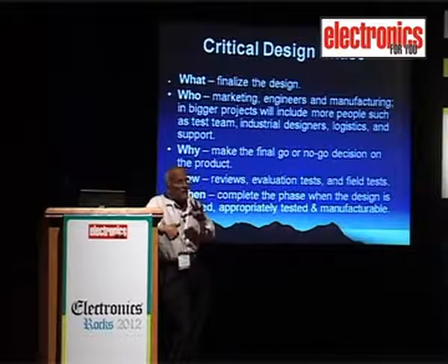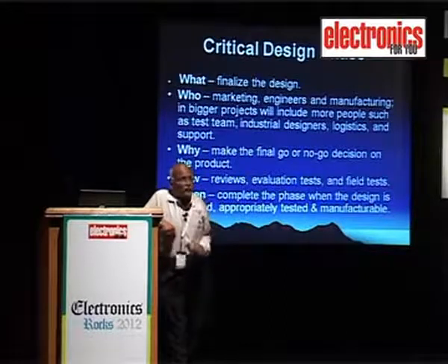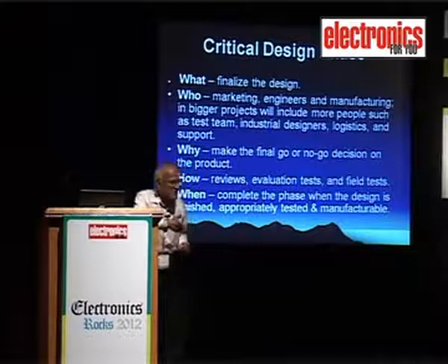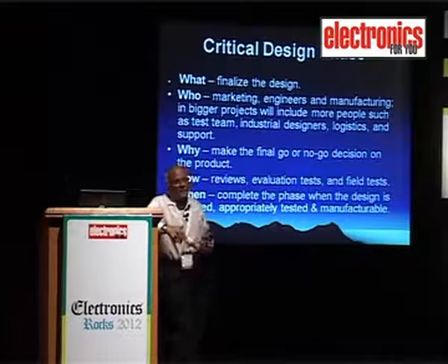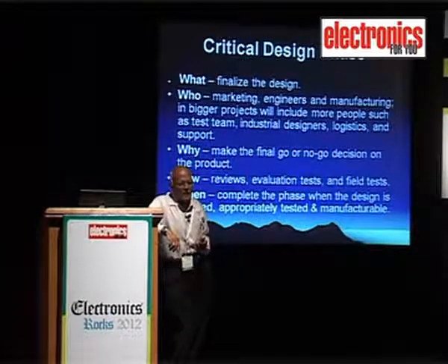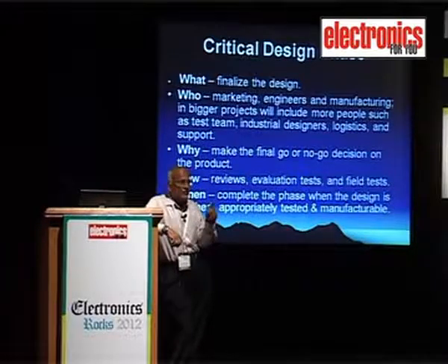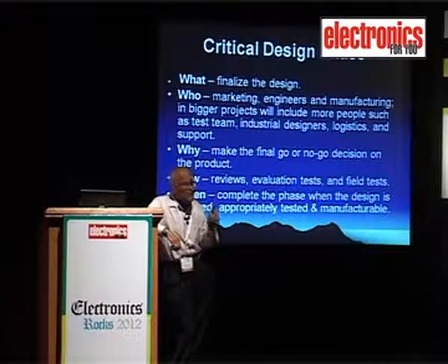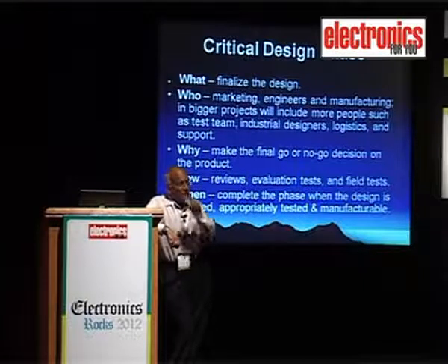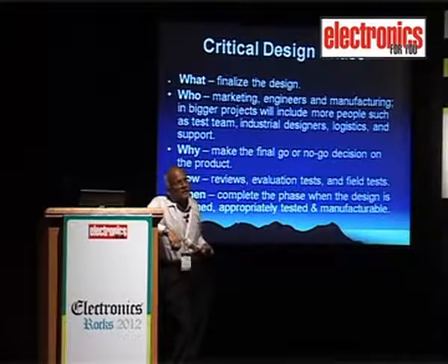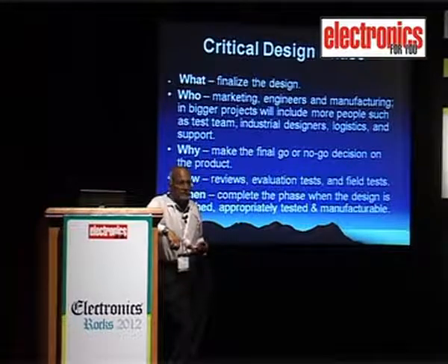I am talking about the appliances that you use in your house, the water filters, the ultraviolet water purifiers that you use at home. That equipment has to withstand 4 kV of surge for 1 microsecond, 50 microsecond, that the surge lasts in the case of a lightning.